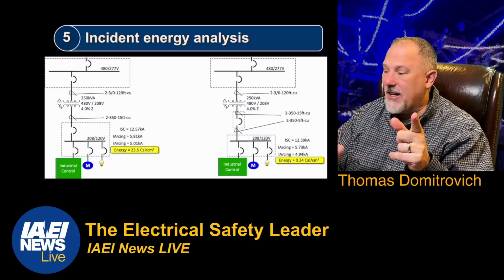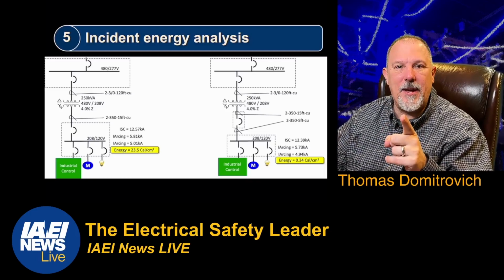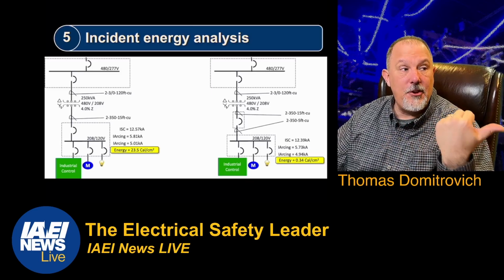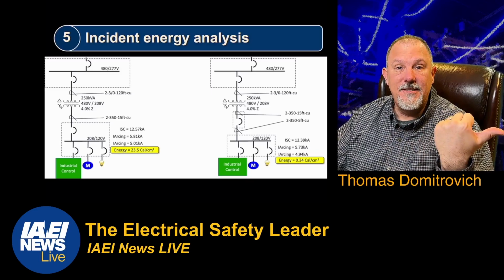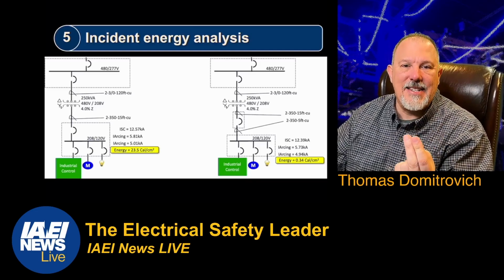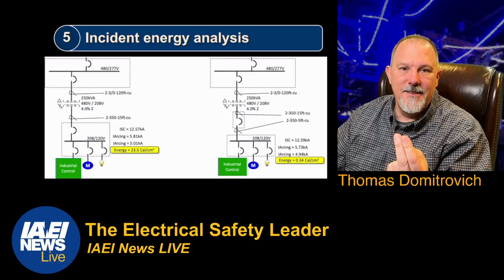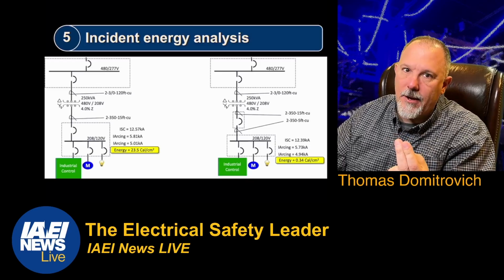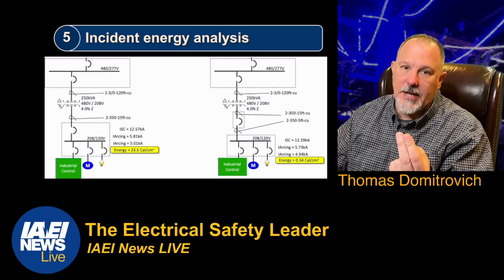And because that disconnect is probably right next to that panel board, lock and tag it out, you can see the disconnect. You know you've opened the right one. You know you've locked and tagged out the right one. Lookalike equipment ain't gonna sneak up behind you and bite you.